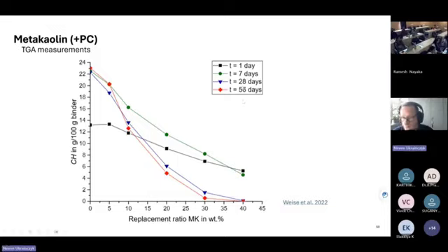After 56 days, we crushed the paste sample, dried it, put it in the TG, measured the TG, and this is the result. And now you can calculate all these points. With the method I just showed you in Python, you can calculate the degree of reaction of metakaolinite.